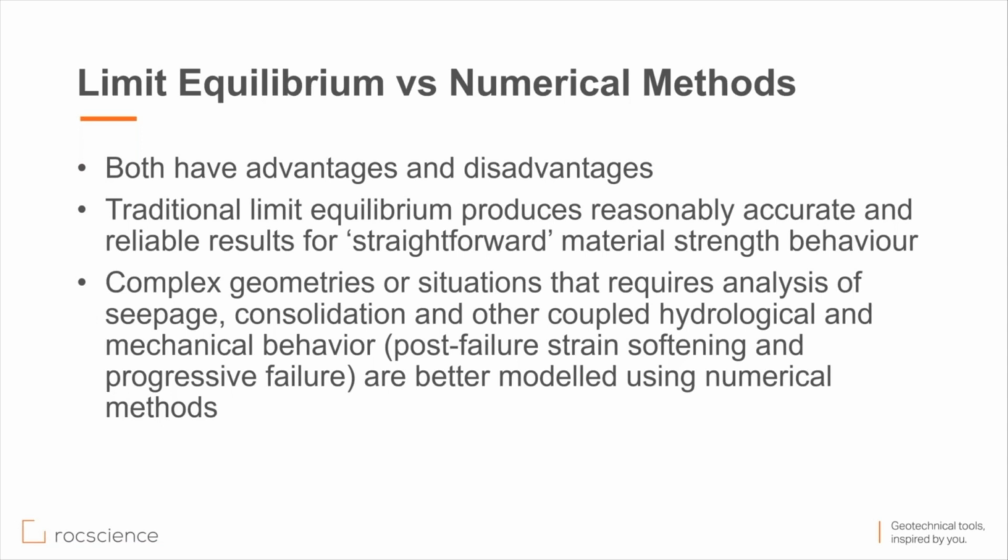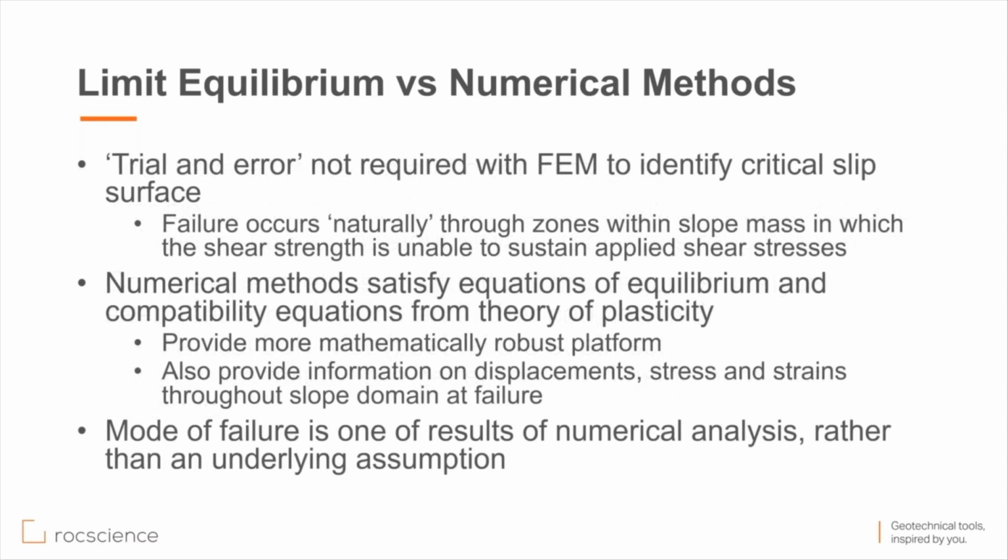When situations are complex and you have coupled behavior, you have sophisticated material strength behavior, you may be better off using numerical methods. And numerical methods, even for the simple situations, will give you another result that can help you ascertain whether your limit equilibrium results are acceptable or not.